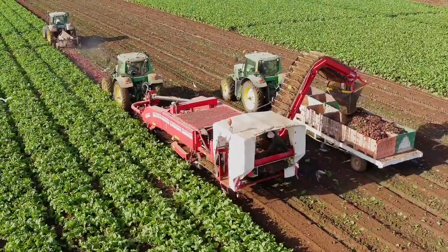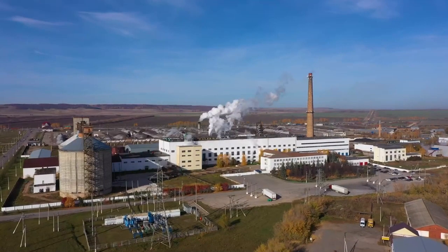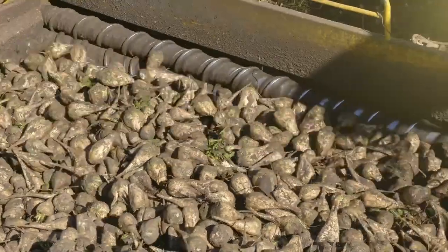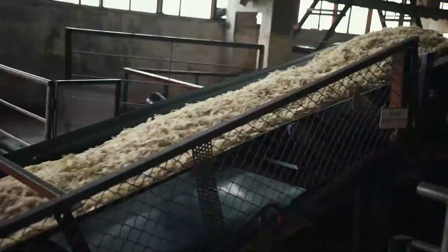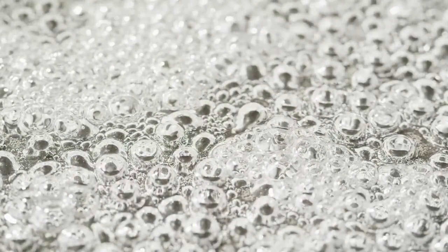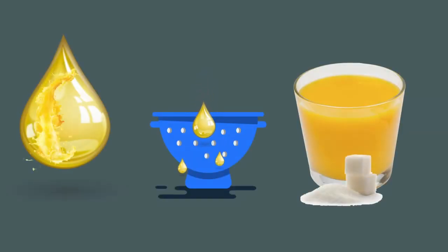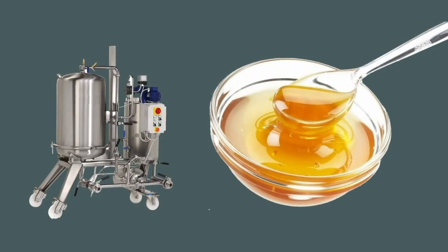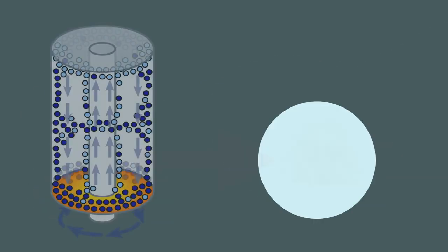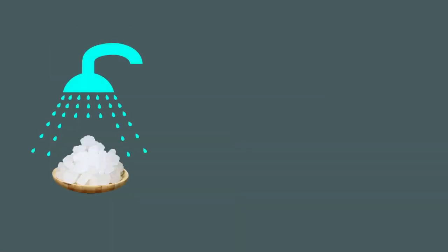Sugar beets processing is an important technological operation when obtaining sugar. Usually, the process of sugar obtaining includes beets clearing from soil residuals, cutting beet shavings, production of beetroot juice by diffusion method, juice purification using reagents, juice thickening and its filtration, increasing the sugar content in the resulting syrup, cooking sugar syrup under vacuum to obtain massecuite, processing in a centrifuge to separate sugar crystals, whitening of the obtained sugar by washing with hot water, drying, cooling and packing the sugar.